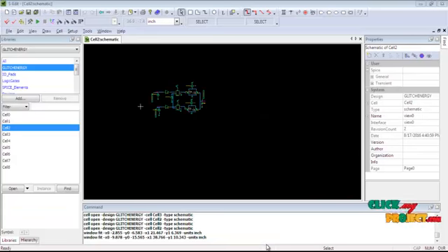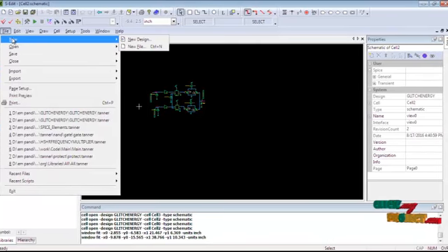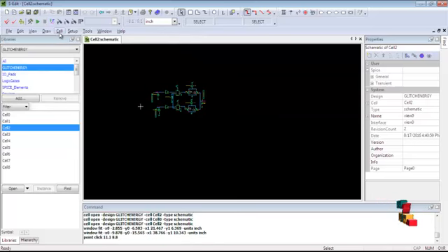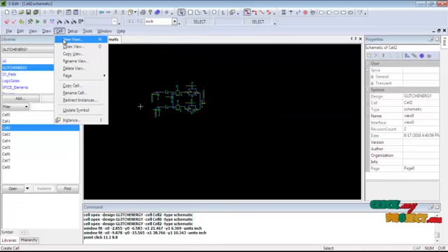Next, we see the running process of our product. Our product is done in CMOS technology using the Tanner EDA tool. This is the Tanner EDA tool, specifically the S-Edit and SPICE simulation tool. First open the file and select New and New Design. Now the window is open. Then we select the specify cells, for example cell 0, cell 1. First create one cell. That cell is cell 0.